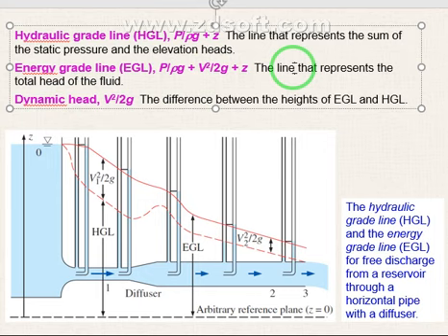Now, when we have small pipes, as I told you, we have continuity of flow. The flow here is going to be the same in the small radius pipe and the bigger radius pipe. In this side we will have high velocity, and here we will have a small velocity, because the flow equals V times area. Area here is big, but area here is small. So velocity is bigger here and small here. That's number one you need to understand.